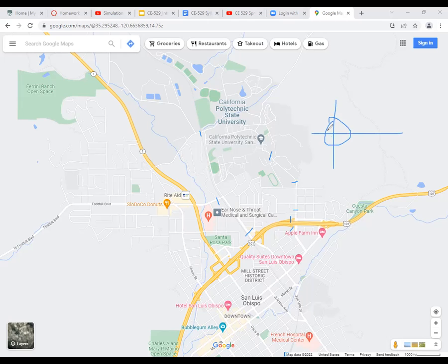If you're modeling just one intersection, and you have turning movement counts at all locations, then you have the origin destination essentially. Right? You know what traffic is going through, what traffic is going from here to here, and all those four approaches, right?